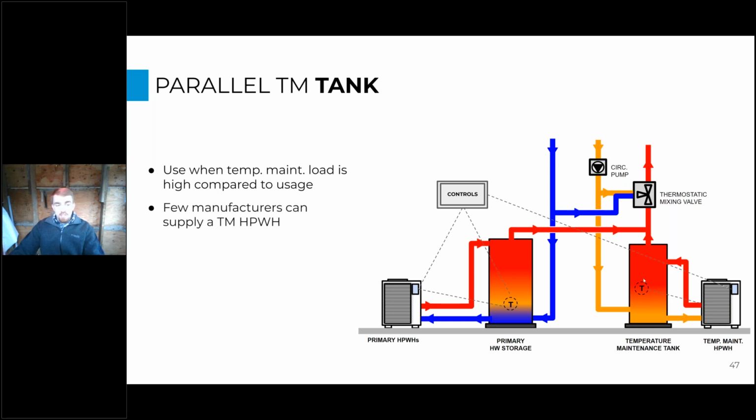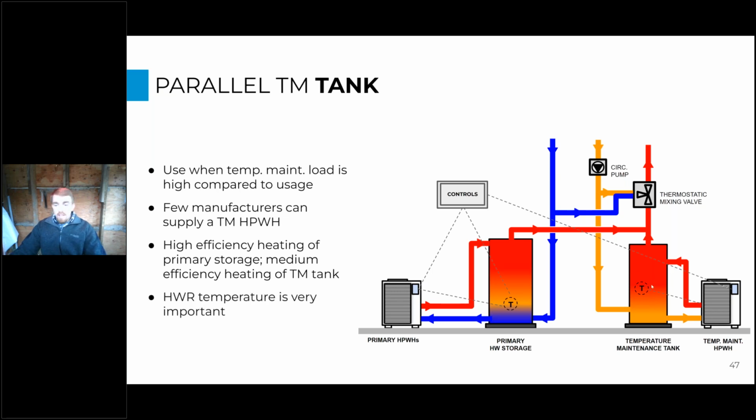And so the challenge here is there's only a few manufacturers that can supply a heat pump that can handle those high entering water temperatures. And as I mentioned here, the efficiency of this primary system is really, really high. And then the efficiency of the temperature maintenance system is still pretty high, still much higher than electric resistance. And then a reminder that the return temperature back to this tank is still really important, because there's still limitations even for heat pumps optimized for this kind of load.